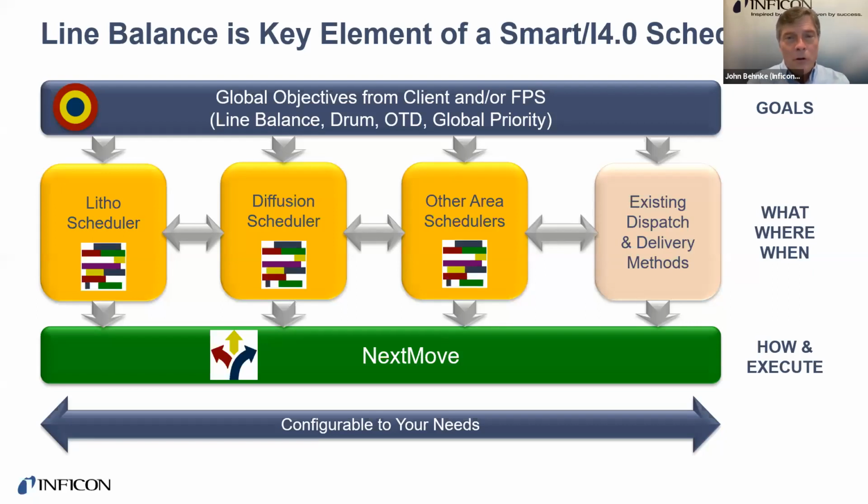And so it's very important that you've created a model and an understanding of the non-linearity such that you can then feed to the other little local optimization engines what you would like to prioritize. So if you're creating a scheduler on the global objectives, and we see litho on the left here, well, litho drives linearity. We just discussed that because it's reentrant. You need to determine and tell that scheduler which layers are more important to improve linearity.